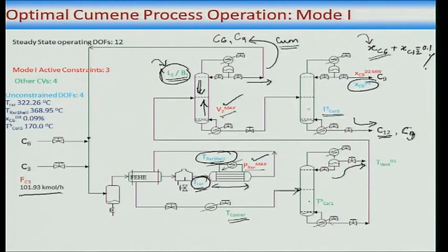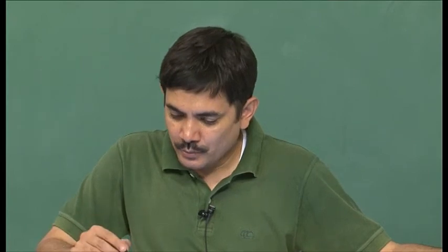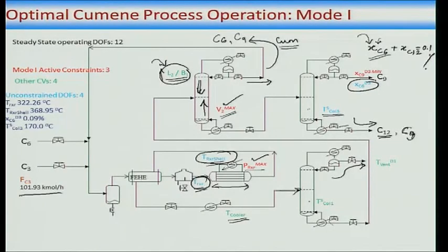It is economically important because V2 max is active for selectivity. If I try to increase throughput, this one also goes active. And what that means is, well, let us see, how do I put it? What that means is that how much impurity level I allow here sets how much impurity level I allow here, and that sets how much steam I consume here. So, my total steam consumption is this plus this, the boil up here plus the boil up here.